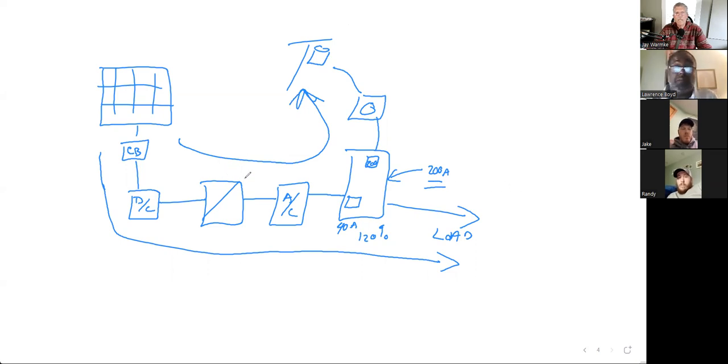So how do we size the inverter in a grid-tied system? It's dependent upon the size of the array, not the size of the load. Okay. That makes sense? These things are correlated. They don't have to be exactly the same, but they're related. In fact, in today's world, they're typically not exactly the same. So for example, if I have a 5 kW solar array, you might think, okay, I need to have a 5 kW inverter. But you don't necessarily have to have it.